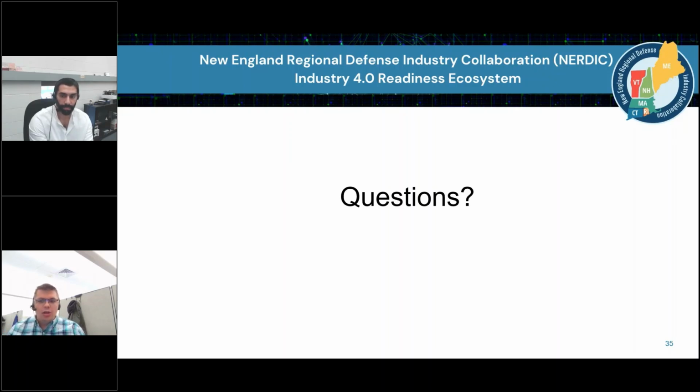That technology is a bit newer than power and force monitoring. It's a little bit harder to deploy because the vision systems are more complicated, but it's definitely out there. And if power and speed are an issue, you can definitely use a system like that to turn a standard industrial robot into a collaborative robot much more easily.